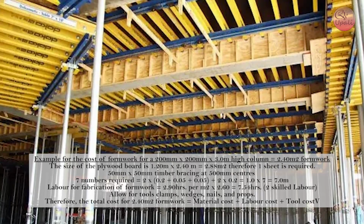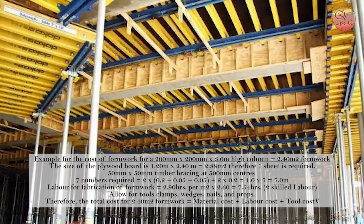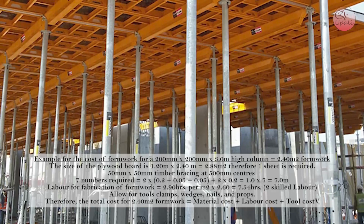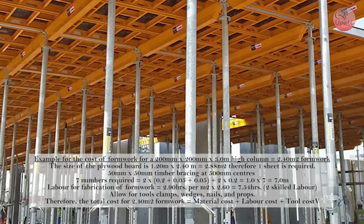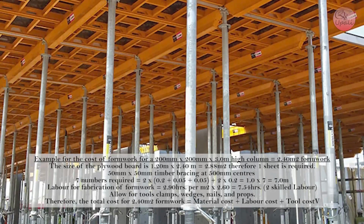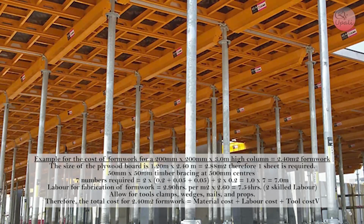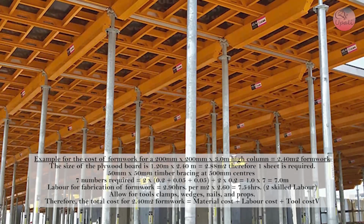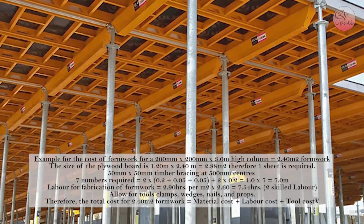Labor for fabrication of formwork equals 2.9 hours per meter square into 2.6 equals 7.54 hours for skilled labor. Allow for tools, clamps, wedges, nails and props. Therefore, the total cost for 2.4 meter square formwork equals material cost plus labor cost plus tool cost.